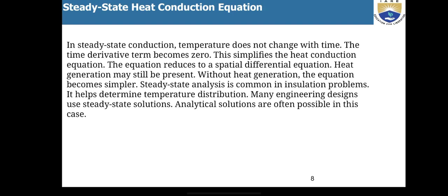Now moving to the steady state heat conduction equation. In steady state conduction, temperature does not change with time. The time derivative terms become zero. This simplifies the heat conduction equation. The equation reduces to a spatial differential equation. Heat generation may still be present.